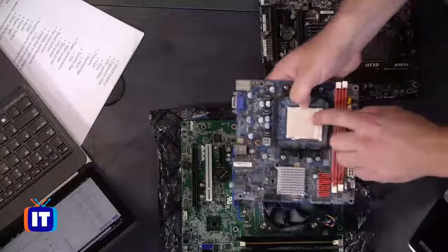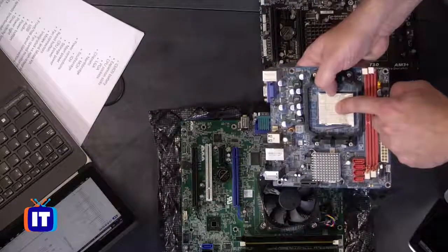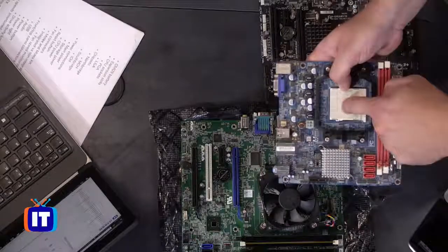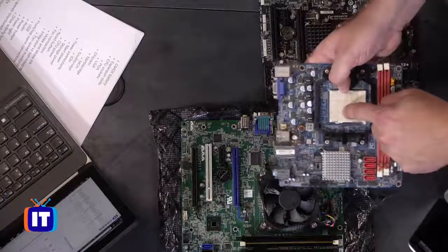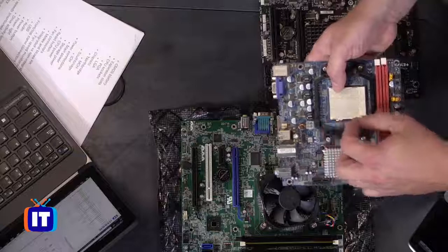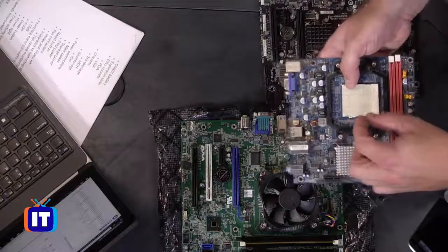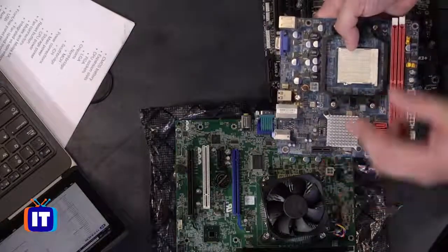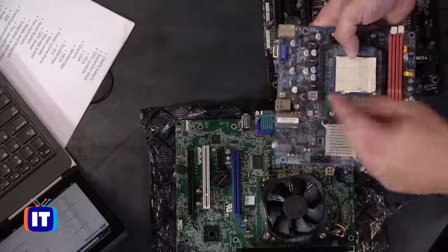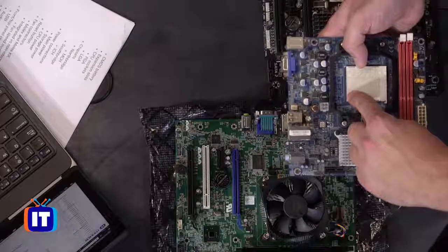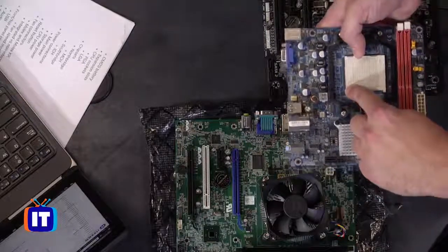The other problem is if you look at the socket itself here on this motherboard, these pins, in this case, the openings are very, very small. And it's very easy that if you were to install a CPU, you could potentially bend the pins, all right? So they came out with this unique design that actually moves. I don't know if you can see in relationship to my finger that the socket is actually moving from side to side. What it does is it opens up this socket and allows you to just drop the CPU in, based on a marking on the socket itself and a marking on the CPU that tells you how to align it so that you don't install it wrong, right? Because that would definitely cause pin bending.